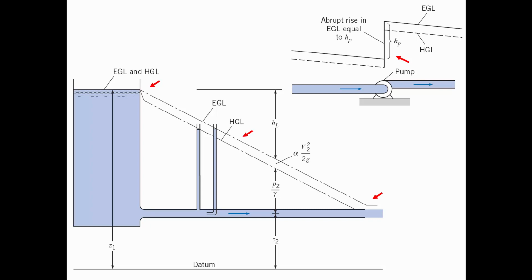As water goes through this pipe, it's not losing elevation, right? It's a horizontal pipe. So it's not losing energy in the form of Z, and it's not losing energy in the form of velocity. It's not like as the water moves from left to right, it's slowing down, because if it was slowing down, continuity wouldn't apply. Q in and Q out have to be equal.